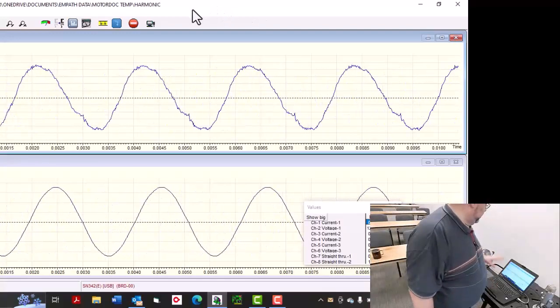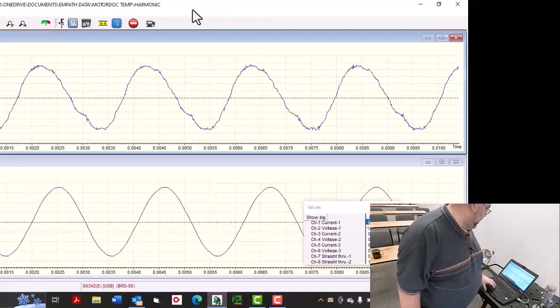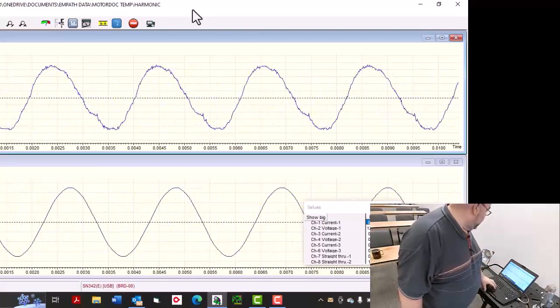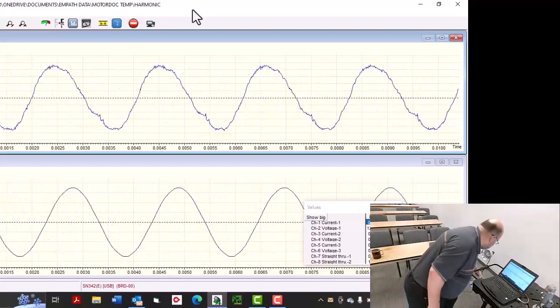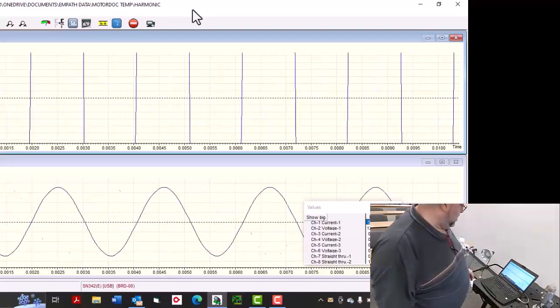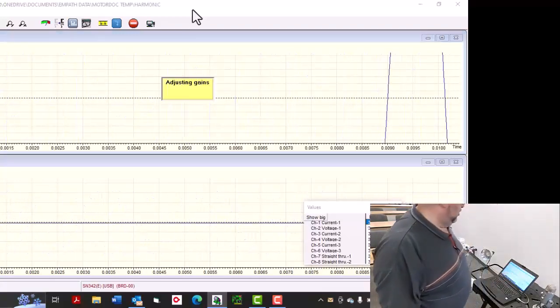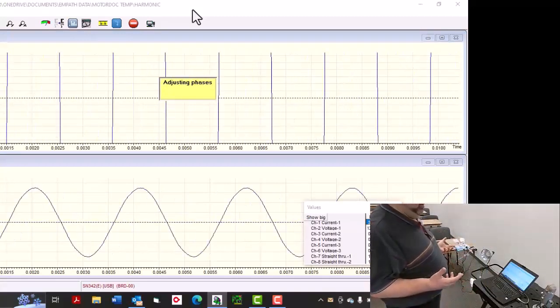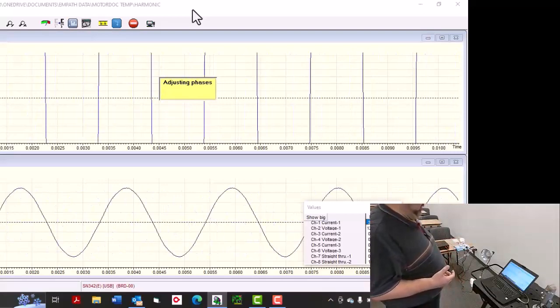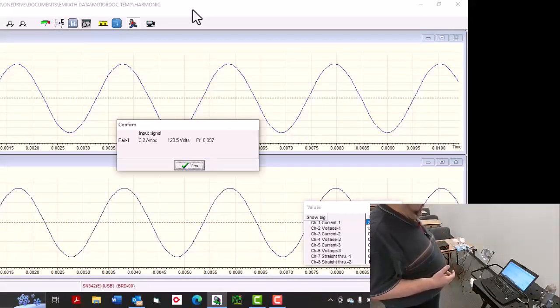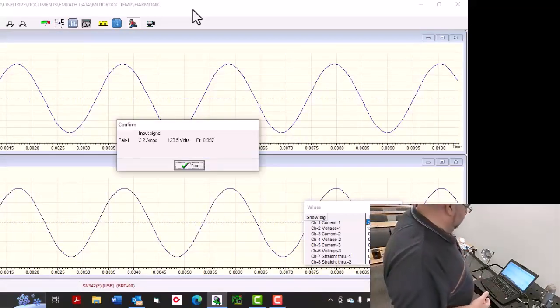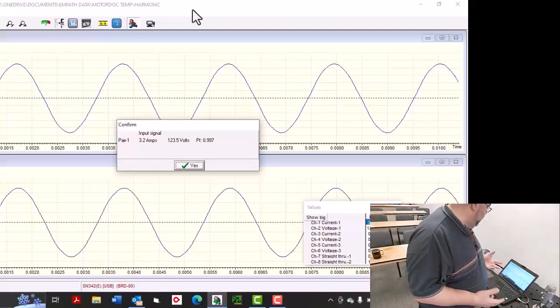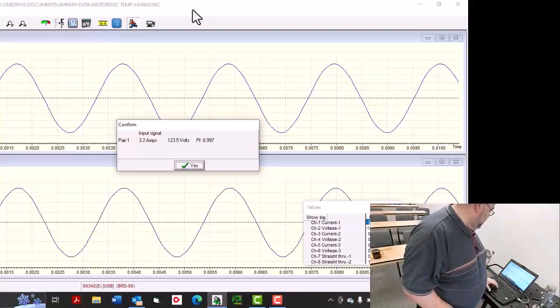So all of this goes back to a 200 amp panel and back. So let's go ahead and we're going to turn on our linear load first at 10 times. So this should be 30 amps? Or 3 amps, I should say, something like that. Let's get it down here. So about 3 amps. So 3.2 amps, 0.997 power factor.